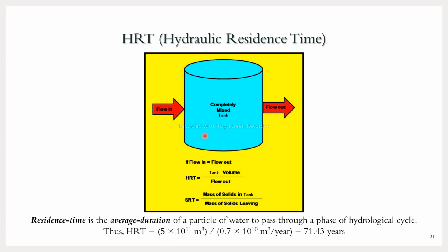Activated sludge basically means the bacteria present inside the water, the sludge that is activated. Activated to do what? Activated to treat the water, to treat the BOD content, that is the measurement of the biodegradable compounds present inside the water. So as time passes, they consume the pollutants present in the incoming water, and they grow in numbers. So at a certain rate, they must be taken out also. Otherwise, they will form chunks of biomass inside the water and they will float, and you will see froth floating on the surface of the tank, right?